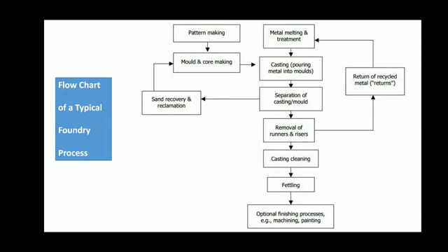Once again, in the next run we can melt it and use it. Similarly, in the previous process, that is separation of casting and mold, suppose we are talking about sand casting, we will break that particular mold. Whatever casting sand is available, we can once again recover and reclaim, reclaim meaning reuse. Once again, that can be used for mold and core making.